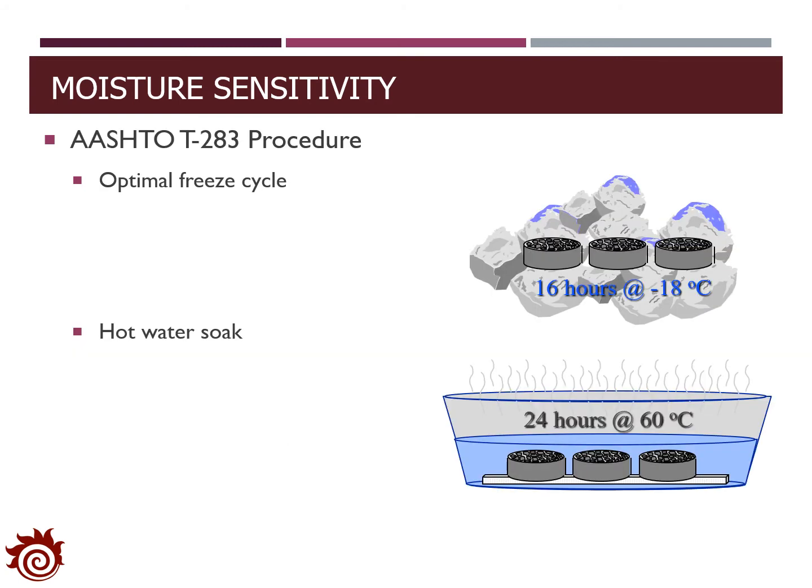In the analysis, we will also apply 1 freeze-thaw cycle for the saturated specimens. At first, the specimen will be stored at a temperature of minus 18 degrees for 16 hours, and then it will be soaked in the water with a temperature of 60 degrees for 24 hours.